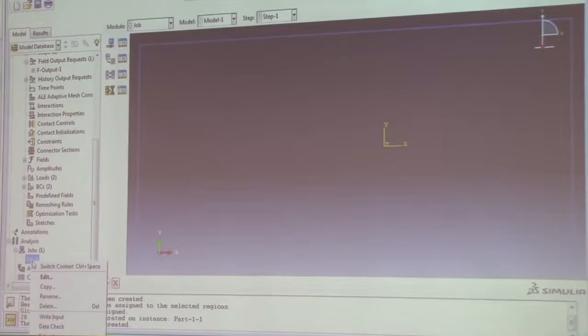Could you please repeat? Say if your element distance doesn't split evenly into the length of your truss, what happens? You can set it differently, one by one, define it in the way you want. I just use 0.2 for the whole model, but if you want, like, 1 element here and 10 elements here and 2 elements here, you set them one by one separately.